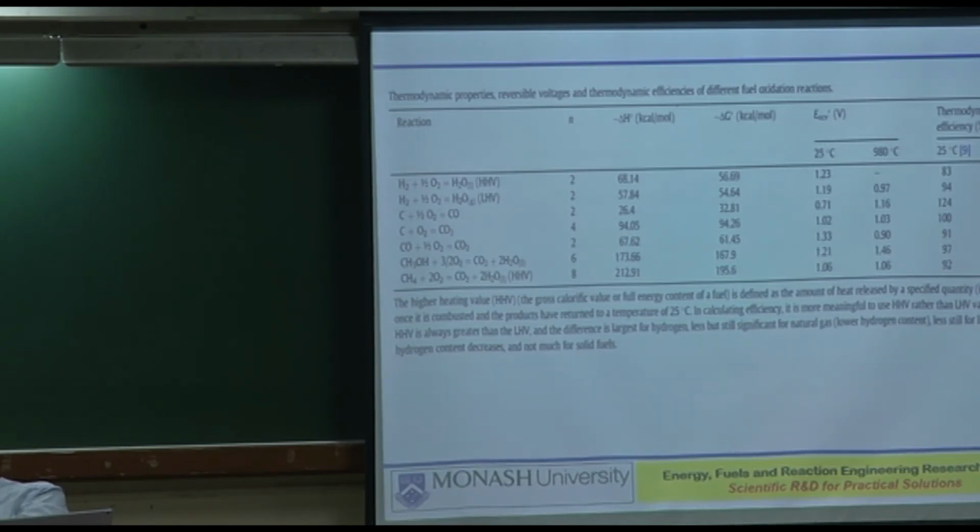What I'm saying is that if, in the denominator, you are burning say 100 units of coal, it has a certain energy value. In terms of the higher heating value, it has a much higher value. On a lower heating value basis, the total energy content is much lower, simply because the enthalpy is taken away by the non-condensing water vapor.